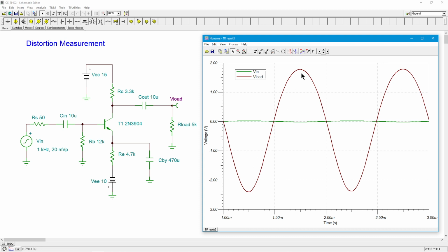So you can decompose any non-simple sine wave into a whole bunch of sine waves. That's basic Fourier analysis. You take a non-sinusoidal waveform, I don't care what it is, square wave, triangle wave, a ramp function, or a squished, manipulated kind of sine wave like this, whatever it is, you can decompose that into a whole bunch of sine waves. So you start with the fundamental, which is the original sine wave, and then we add on all of these integer multiples, these harmonics, at the appropriate amplitude and phase. If we do it right, we get the appropriate shape out of the resulting signal. We don't really care how that happens right now. We just know that it does happen.